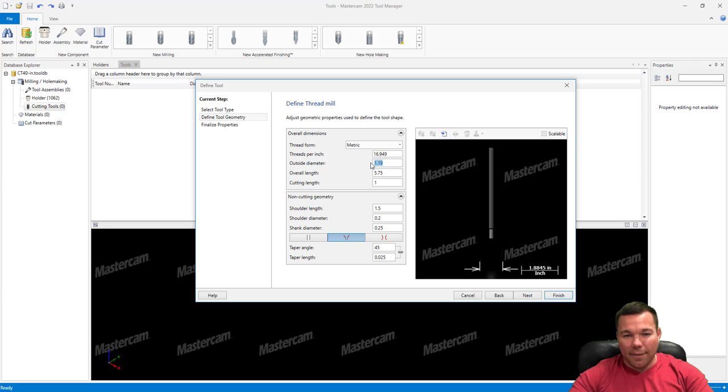And this doesn't have to be perfect the first time. If you're putting it in and it's not perfect the first time, that's fine. All you're going to do is just put an offset in your tool at your machine. Just tell it that the tool's a little bit bigger than what you think it is, and run it. See if it cuts to size. Whatever it's off, that's how far your tool's off. So you can come back and adjust this once you figure that out. This is a hard tool to get a perfect measurement because it's a single flute. 3 flute is another one. Unless you have a V mic, very difficult to measure those. Okay, so 1.19 our outside diameter.